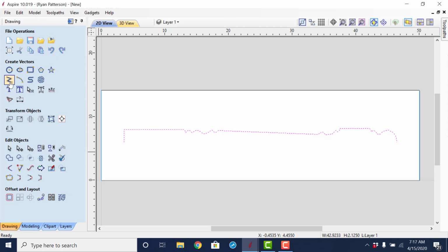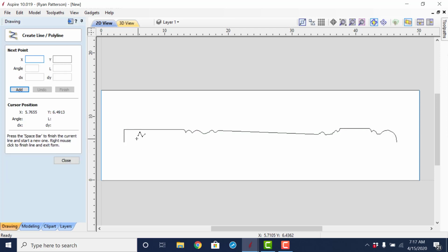So I'm going to come into Create Vectors under the Line tool and draw a line from the endpoint up. This is going to be the one side of the rail curve. Now, I wanted to go up the distance of the Y value. Now the Y value is a little obscure because it is the circumference of that 4.5-inch diameter that we entered in. So if I'm not sure what that is, I could just simply in that Y value hit Y, then equals. That enters it in there and click Add.